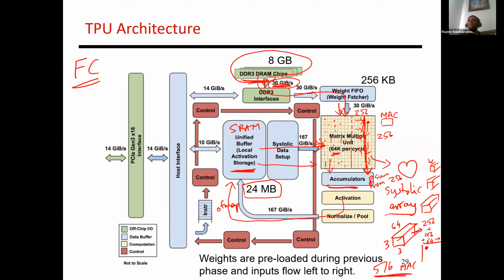The TPU makes that a little bit more efficient by using what is called double buffering. In each one of these cells, there are two weights being stored. W1 is the weight that's currently being used, and hopefully I'm going to be busy doing all kinds of number crunching for a while. While that is happening, I'm going to start fetching the weight for my next computation. That's how I try to stay one step ahead. Okay, and it takes me a large amount of time to bring in W2 and place it over here.